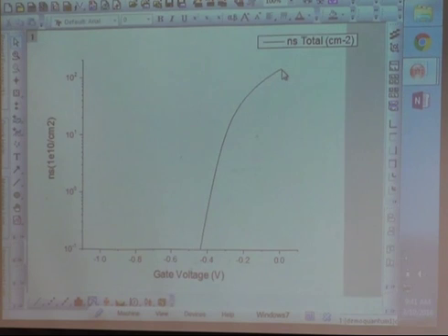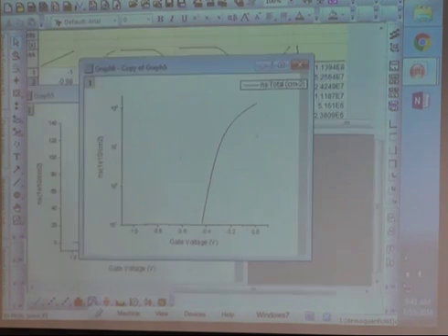When you are in this situation, you had a lot of electrons, but now you have a very tiny tail. It's exponential decay. That's what you measure when a transistor is switching off. That is actually a measure of the Fermi-Dirac distribution of electrons in the band. So it's called the sub-threshold characteristics of the device. Okay. So, questions on this?